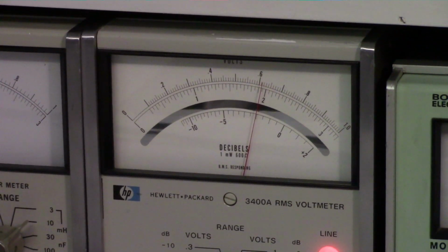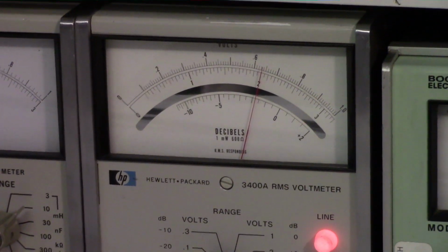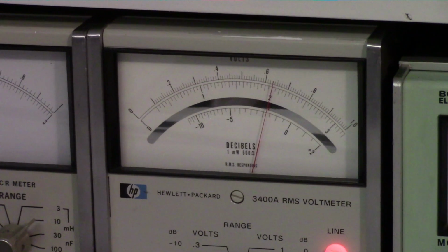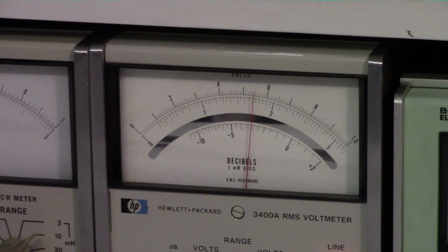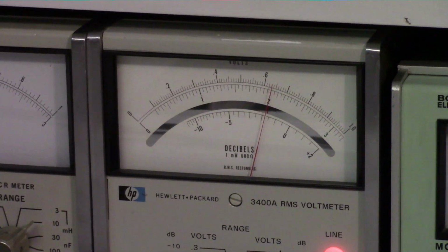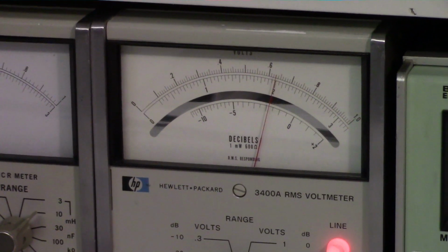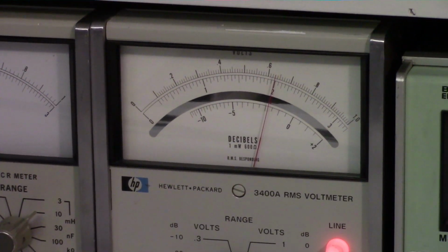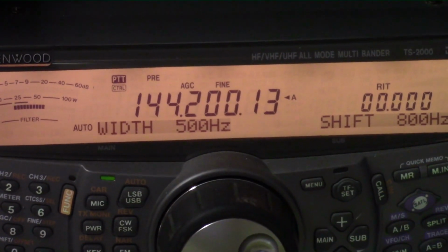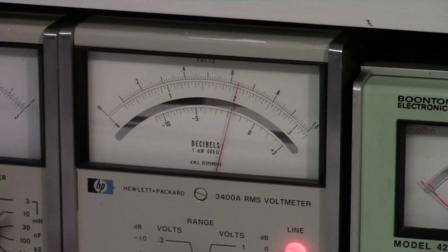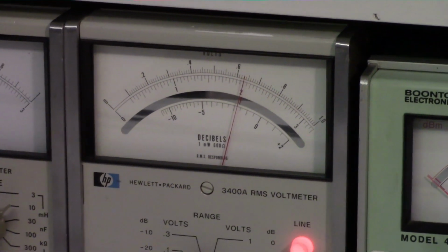Notice we're not going to be adjusting the radio for the exact frequency of the carrier. What we're going to do is find where it actually peaks. So I think someplace right about there is the peak. It ends up being right at 14200.13, and it's really irrelevant. But the point is that in the IF filters of the radio, that carrier now is at a peak.